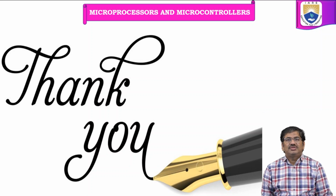The next instruction we have studied is the push instruction, which is for pushing the data onto the top of the stack. The next one is pop, which is for popping the content of the top of the stack into the operand specified in the pop instruction. Next instructions are related to reading a port and writing a port. The IN instruction is used to read the data from an IO device which is connected to the port. The OUT instruction is used for writing data to an output port.